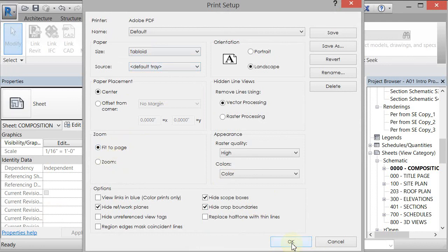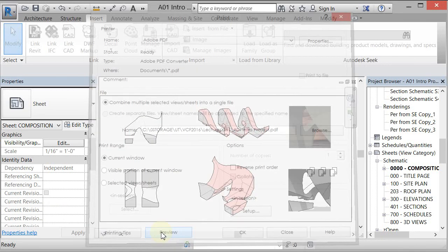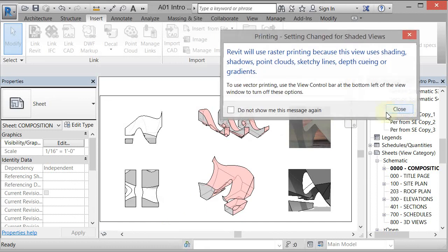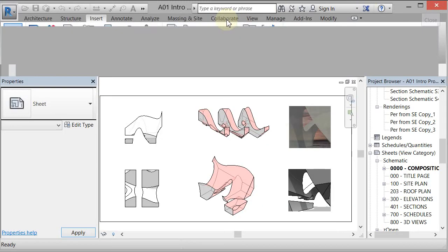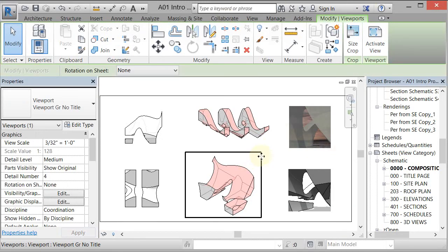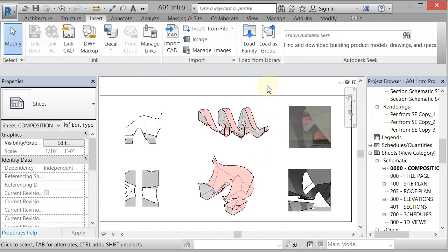But I'm going to click OK, and then if I go to Preview, it will give you a preview of what that's going to look like. If you want to, you would have to go in and set up, this is a 12 by 24 inch page, and you have to set up a custom sheet for that, okay? And remember, this is just a preview. We could go through and print it, and it would print it out quite well. So, all right, that's the quick introduction to importing in Revit and templates, and we'll go over some more specific things a little later.